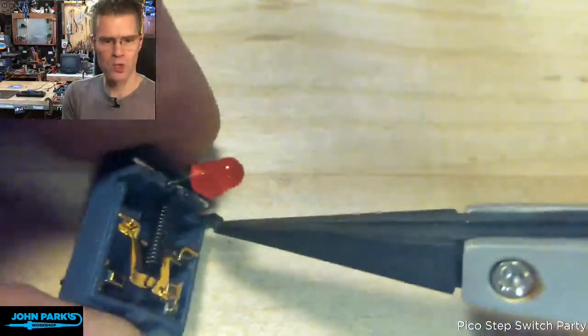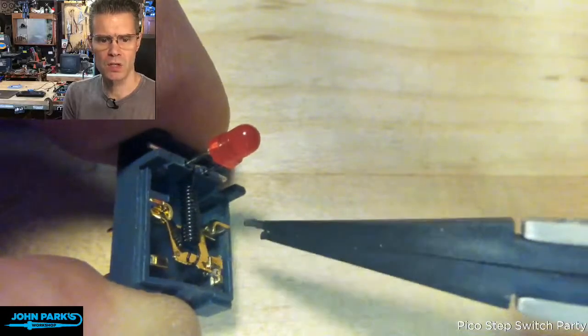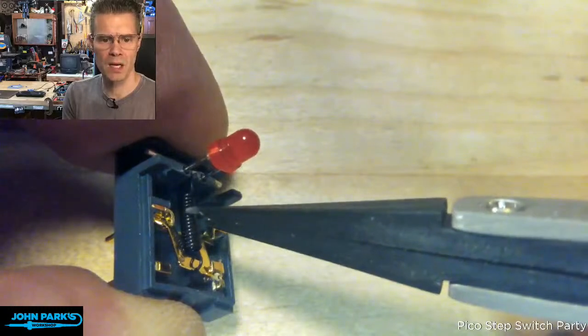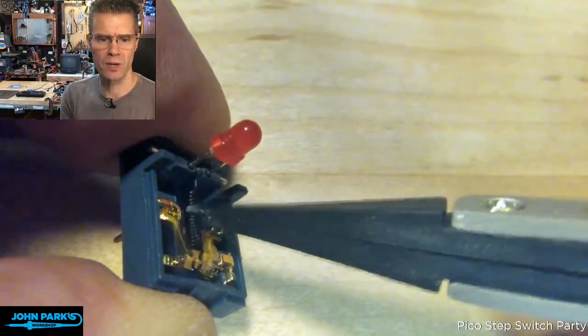So the way I'm using it, I'm using the normally open side. That's the contact that's being made there. So both of these two common legs remain in contact, and then we either break contact on the right side there, or we make contact on the left there.